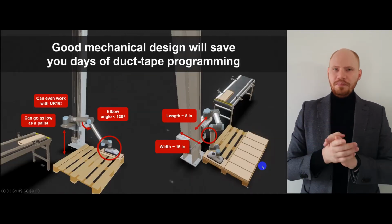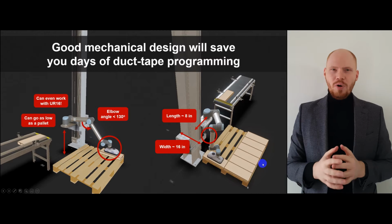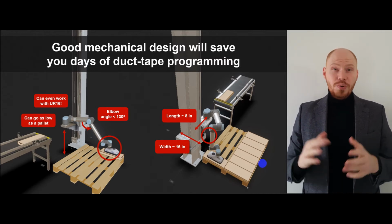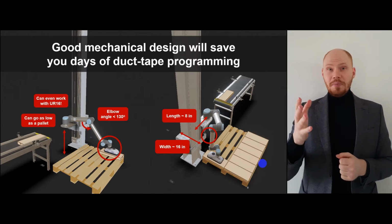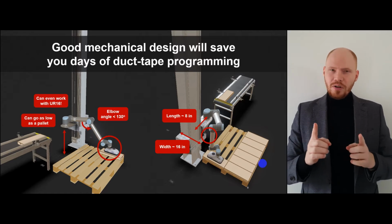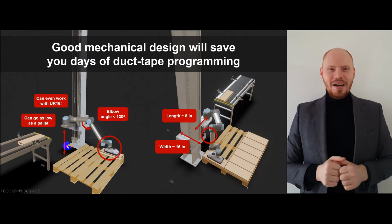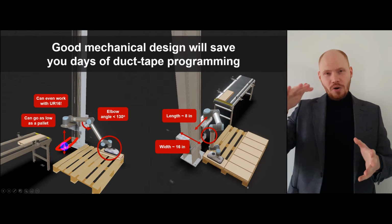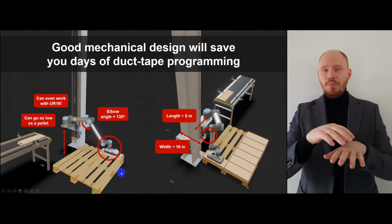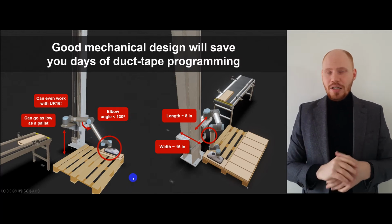A rail-based frame is a bit less tricky than a mobile one, and I believe is more suited for the North American market due to the pallet size. With this in mind, reachability is usually the biggest problem. However, a solvable one. For example, if your robot can go as low as your pallet, you can easily reach the pallet corners with small boxes even without the TCP extension.